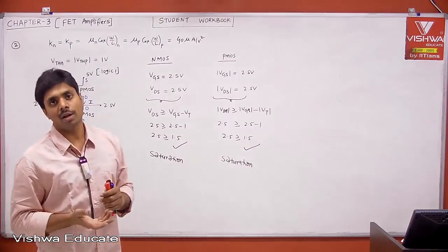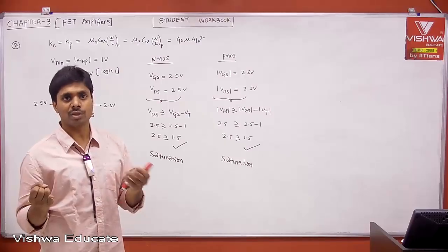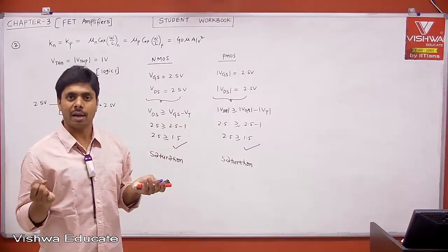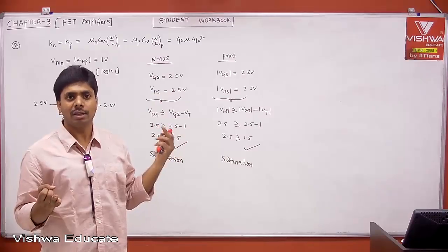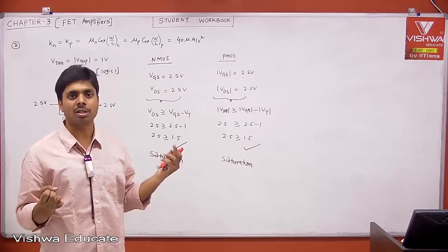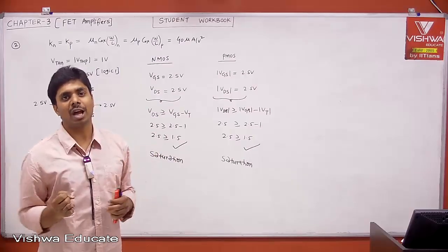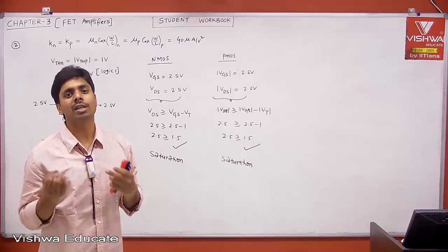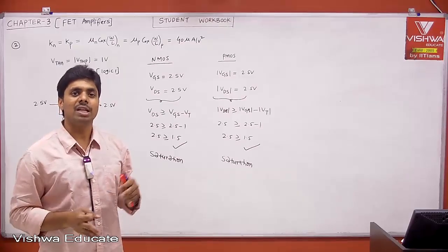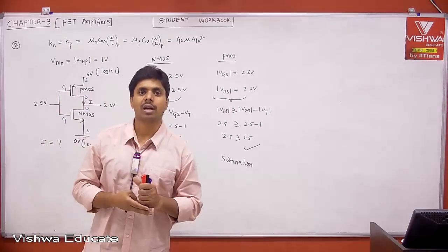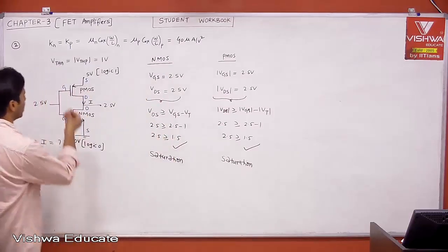Therefore, the total power has dynamic power to charge and discharge the capacitor, which we need, which is changing the state of your circuit. Number 2, static power. If there is no change, if input is constant, then there is a path from power supply to ground, but one of the transistors is off, so you'll get a very small current, which is leakage current or static power. Third one is short circuit or switching power or switching current. That is because of this only. That is what is being asked: what is the switching current.